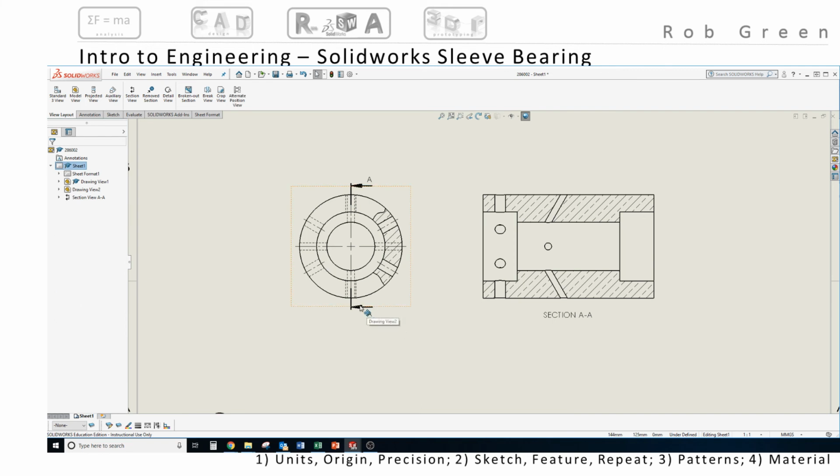However, if you look at these section arrows along with my section blade, it does not look like the finished drawing that we are targeting. This is actually according to a standard that is derived for Europe, International Standards Organization. In the United States, what we're interested in is ANSI, American National Standards Institute, and Solidworks has a complete set of ANSI standards built into it. We just need to turn it on or change it from ISO.